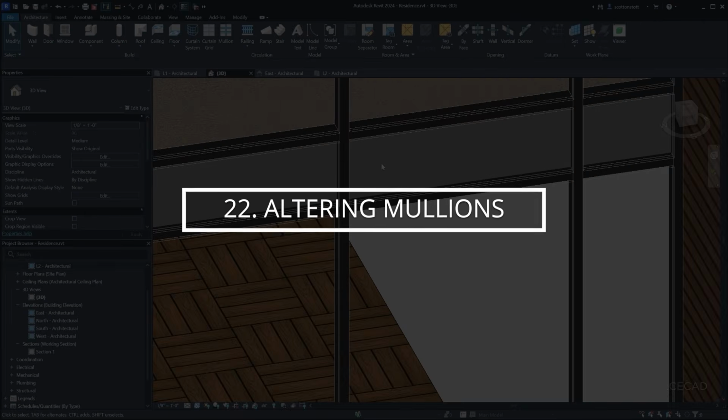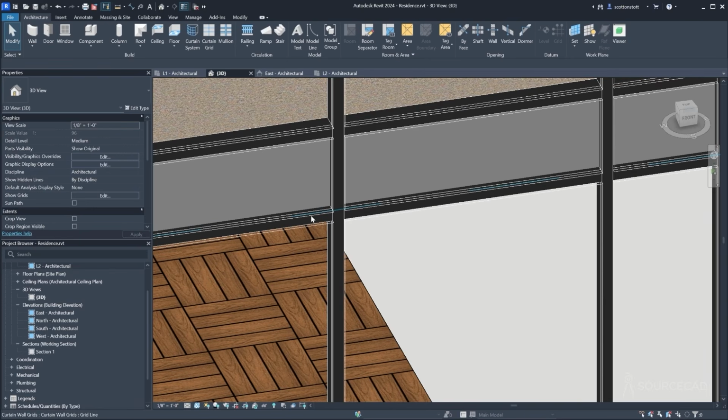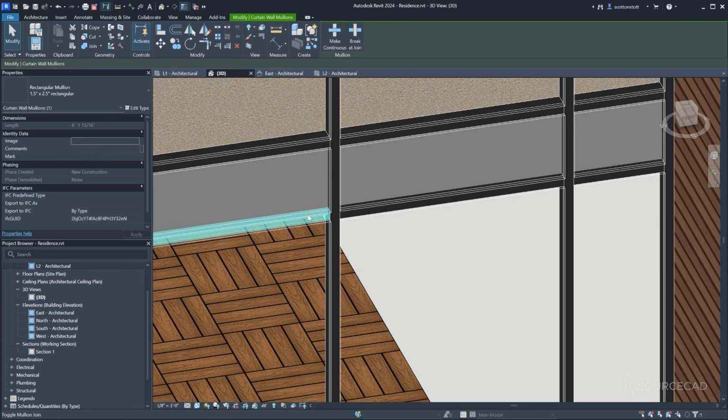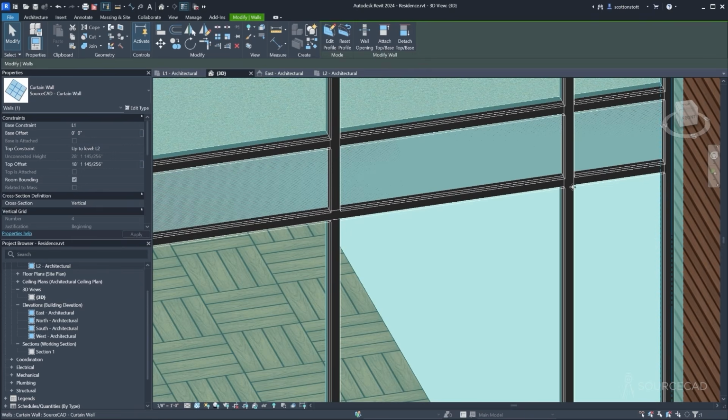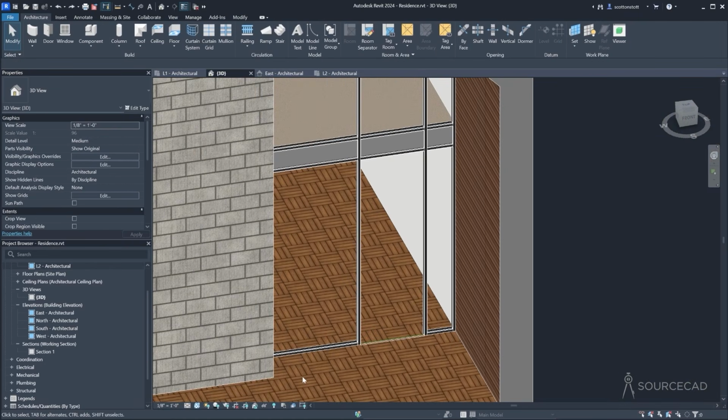If you want certain mullions to go through and not be interrupted, you can select them, like select this one mullion here. And then there's a little grip here. It's hard to see, but if I click on that, this mullion will now penetrate through and take priority over the vertical one. And so you can create these joining conditions where you want this horizontal one to run clear through, or do you want the vertical one to do that? It's up to you. In this case, I'm happy with the vertical ones running all the way through, I guess. So I'll undo, leave that as it was.